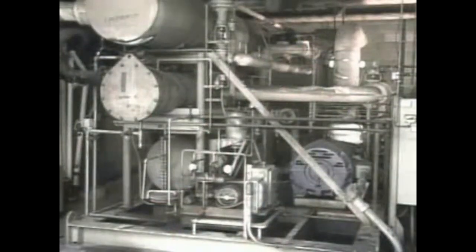Ideally, a vapor compression refrigeration system will run efficiently and practically by itself. Sometimes, however, problems may occur. One of the more common problems that can affect a refrigeration system is an improper amount of refrigerant. The amount of refrigerant can be determined by checking a level indicator on the receiver or by checking a sight glass on the receiver outlet.